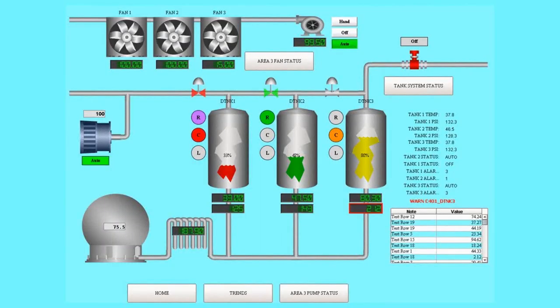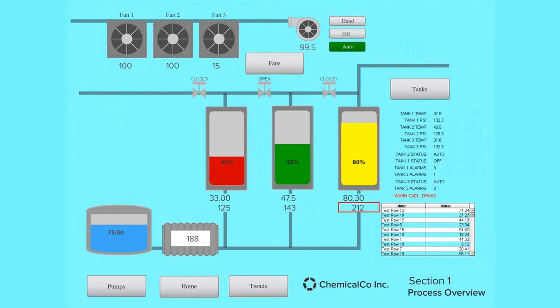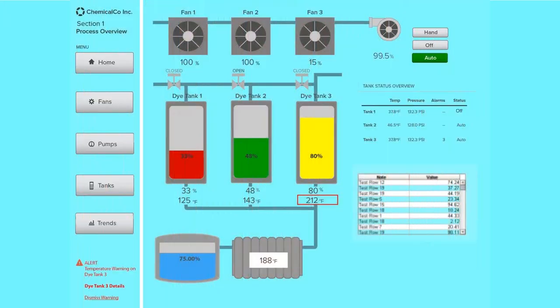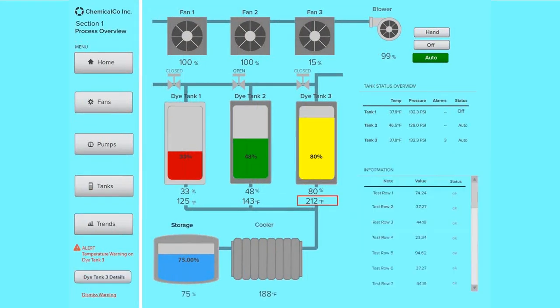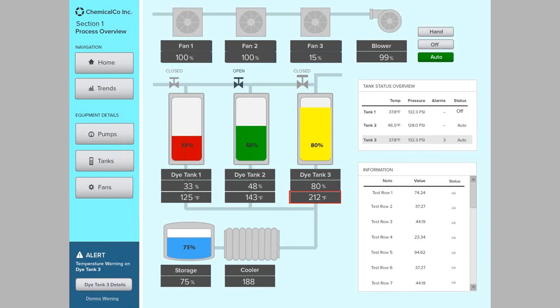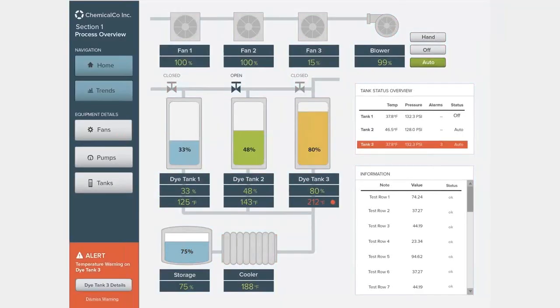So we started off with an HMI that was kind of cluttered and ugly, and then reduced the cognitive load by removing visual clutter and simplifying the graphics. Then we applied a grid and aligned our elements. And then we added icons to our text, labeled our equipment, and introduced an alarm that used plain English, and then made everything more consistent. Then we started working on the visual hierarchy by improving contrast, and then we adjusted our size, proximity, and white space. And then finally, we finished up by using color to better define our important and less important elements.